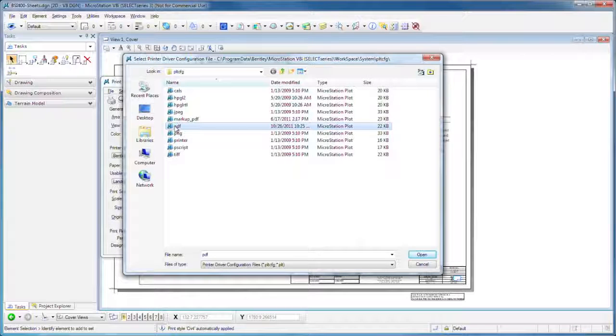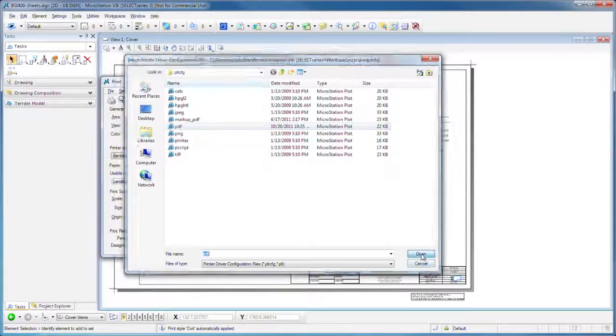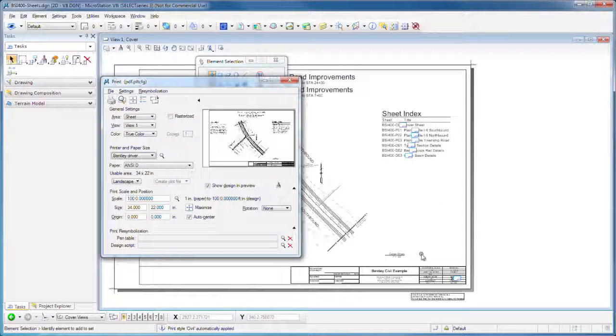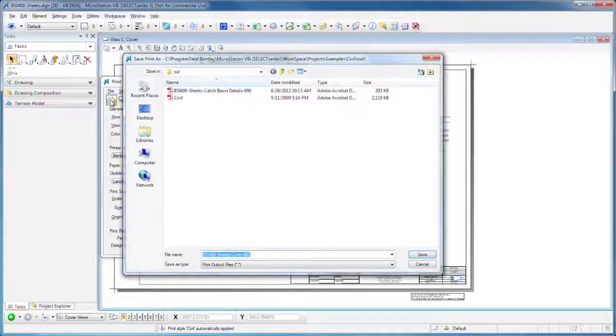You know, there are close to 1 billion copies of Acrobat Reader that can read the PDF files produced from MicroStation. This is something that sets MicroStation apart really from a lot. It's its cooperation with Adobe and its utilization of the PDF file format. So we'll just pick the PDF and say eventually we want this on a D-size drawing, and then just click Print. That's it.